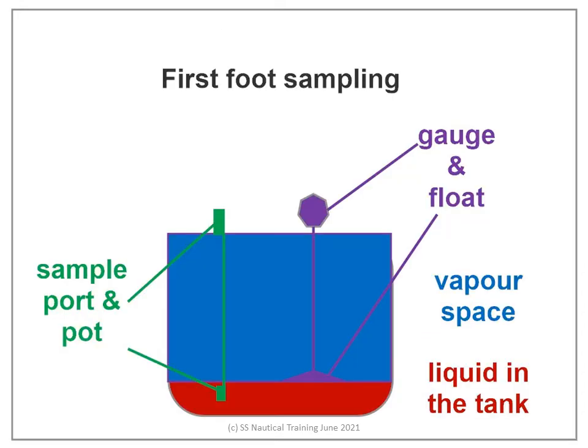After the tank has 1 foot of cargo, cargo loading is stopped. Manifold valve, drop valve and discharge valve are closed. We then start the pump and collect the sample from the first available drain on the cargo line.